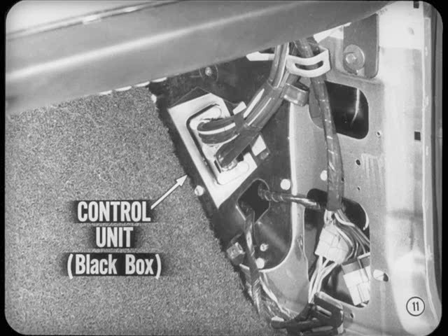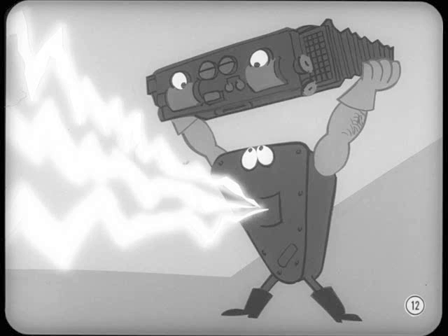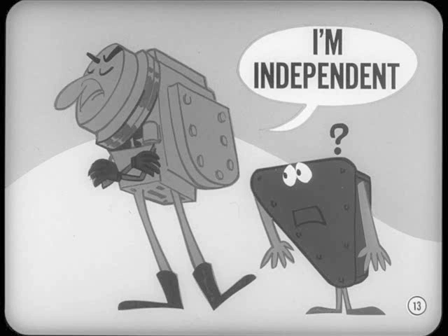The signals from these 3 conditions are transmitted to a black box type control unit located behind the right-hand side cowl trim panel. Inside the control unit, the 3 signals are translated into work orders, which are directed to the various air distribution doors, the water valve, and the blower speed selector inside the control unit itself. The air conditioning compressor clutch is engaged whenever any of the instrument panel push buttons is pressed, except the off button, if the outside temperature is above 32 degrees. The electrical circuit for the clutch is independent of the control unit, so it does not respond to any signals from the sensors or the thumb wheel.